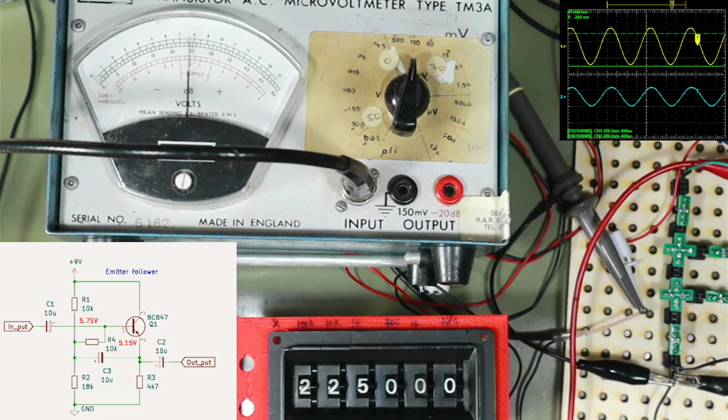Now the reason it hasn't gone up to like the 500k that we were hoping is possibly the fact that there is a voltage difference between the signal here and there. And so it's not perfectly exactly the same. It's not 1 for 1. And so there will be some current flowing through this resistor, and flowing through that resistor will be seen as an impedance for AC, and so maybe that's why we haven't got the full gain.